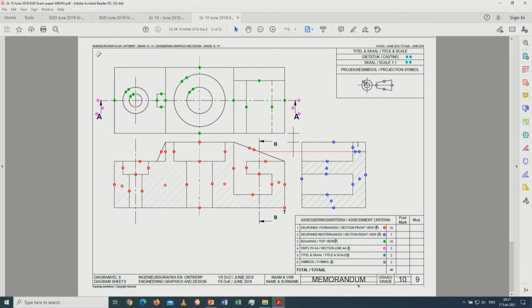From the bottom on its way to the top, it's been cut at that specific point. So the cutting plane starts at that point, and then from there on it goes further down. Can you see it's a casting? There are no seams, there are no solid lines in between, and it's not pasted onto one another. It's one unit melted in. There's your symbol, there's the heading of the drawing.